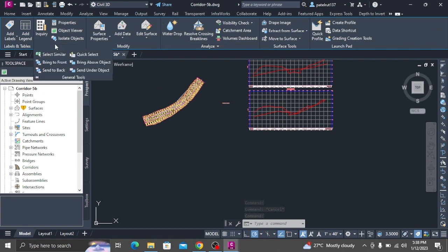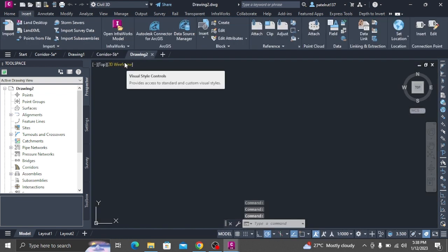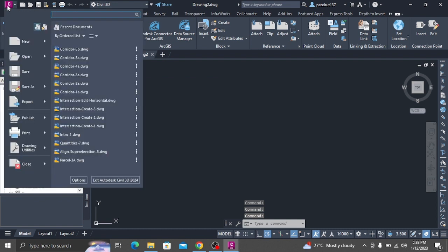In the Corridor Surfaces dialog box, on the Boundaries tab, select the Corridor 1 Median Surface. Right-click and click Add Interactively. Define the outside boundary of the median. Click in Circle 1 and select EPS to define the left outside edge of the paved shoulder. Click in Circle 8 and select EPS to define the left outside edge of the paved shoulder.